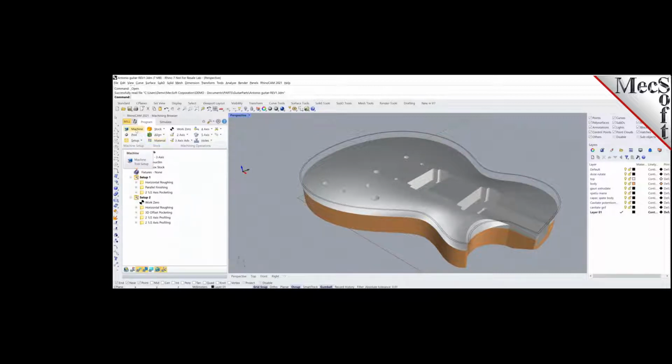The first thing you would do is define your machine tool, select your post processor, and then do any setups. You have a 4-axis, so you might be doing multiple setups, where you machine the part from different orientations. This allows you to do that. Then you define your stock model for your actual workpiece for simulation, and there are some stock model alignment functions here. You can also define what material you want to machine. This is where you're going to do the bulk of your programming. We've got a work zero; you can set up work zeros.